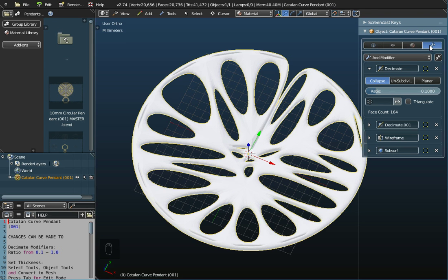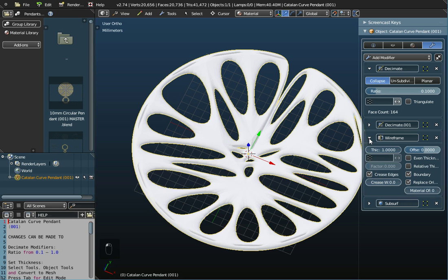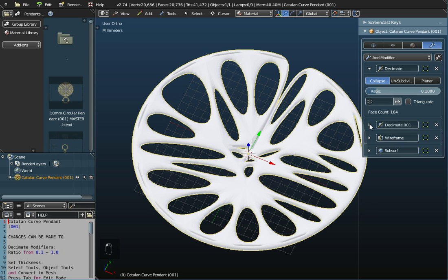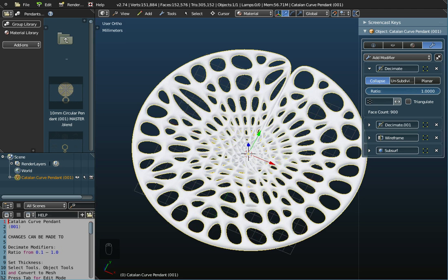Well, if you go to the modifiers panel, one of the panels, the Decimate panel, is open for you. Now, I wouldn't really advise you changing the parameters in wireframe and subsurf, or even the second Decimate. I would stick to perhaps just modifying this value here, the Decimate Ratio. Now, if I click in this bar to the left here with the left mouse button and just drag it all the way to the right, that's actually what the default pattern looks like.